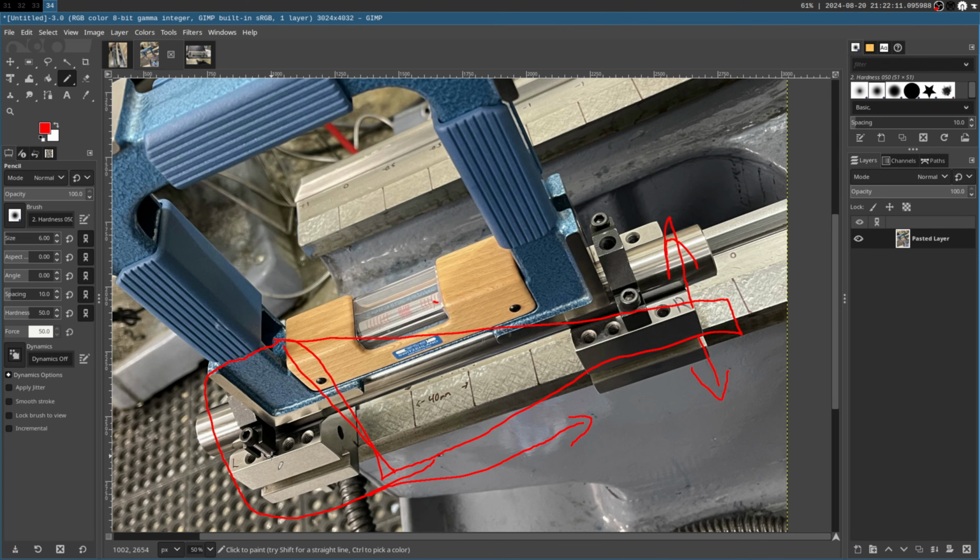Then I know that this raised or lowered relative, right? So it doesn't matter that there's a parallelism error in my actual setup, and that is a variable that we've eliminated. The precision of the rod and all of these things doesn't matter, or specifically just the heights in this case, because the flatness of these bottoms matters, because we're relying on the flatness communicating the surface contact with the bed of the lathe.